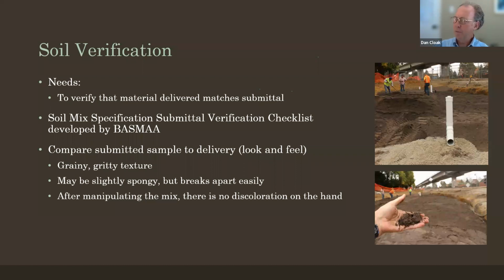And something similar is probably what's happening with bioretention soils, which have been mixed and then are being repeatedly wetted after installation. If they have too much clay in them, you can get that problem of them suddenly showing a very, very reduced rate of infiltration sometime after installation. So that's why the mix exists.